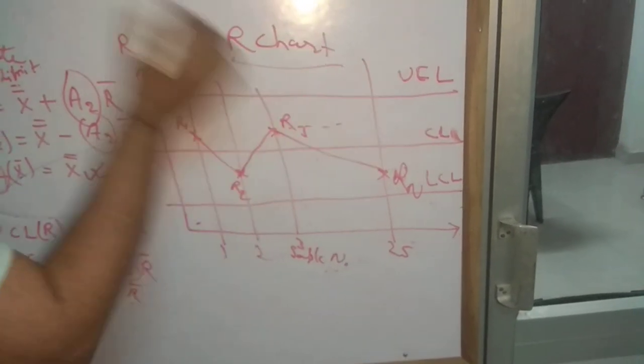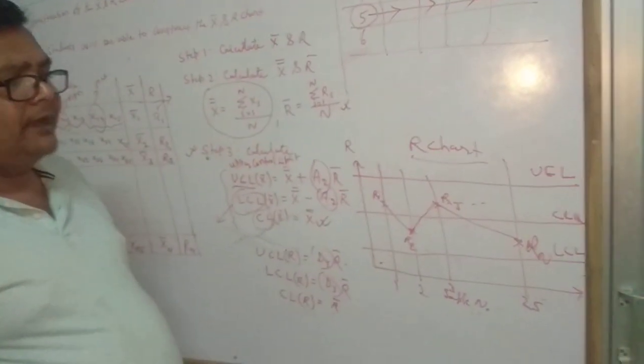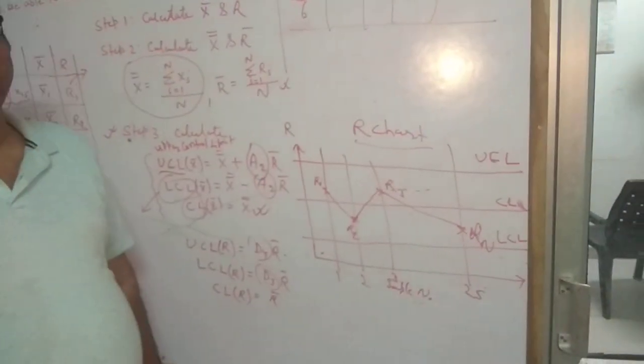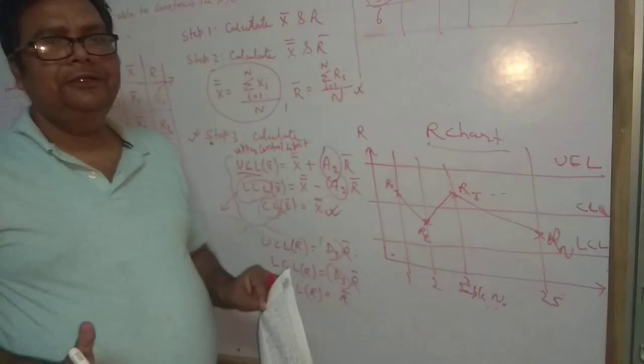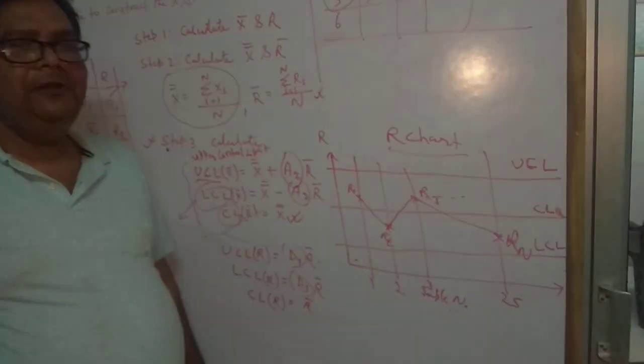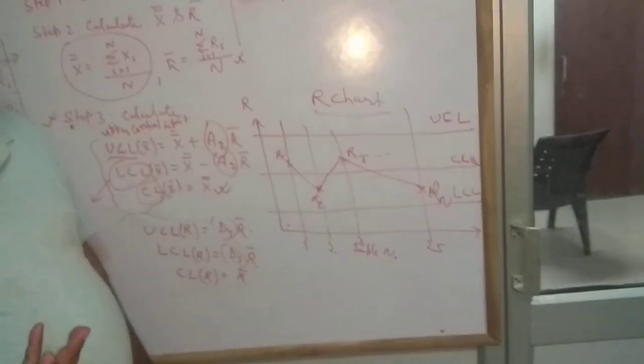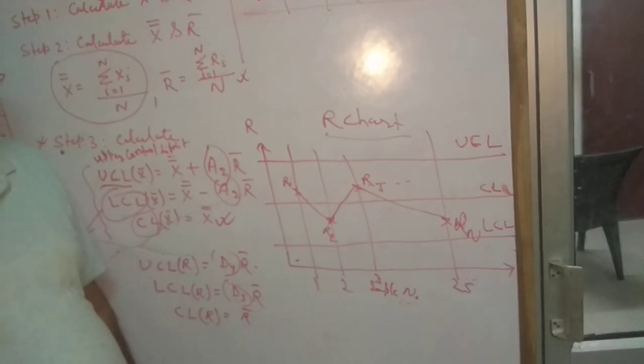One more thing I would like to bring to you is that a single X bar chart or R chart does not portray anything. Both charts have to be drawn simultaneously. Only then can we come out with meaningful conclusions.